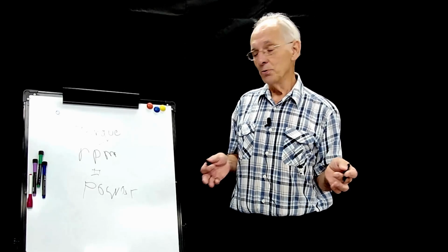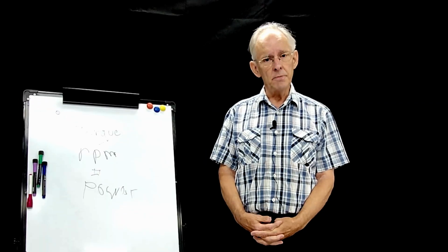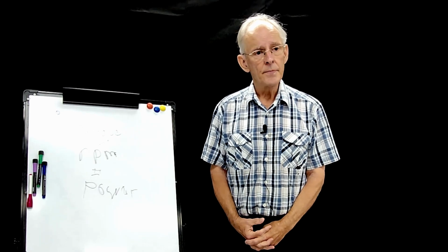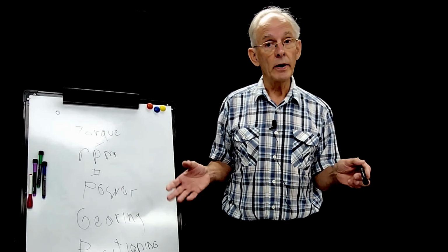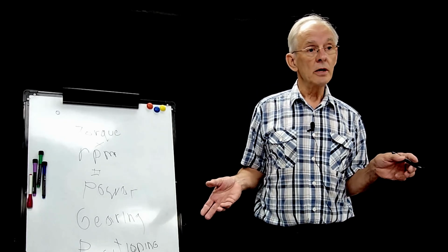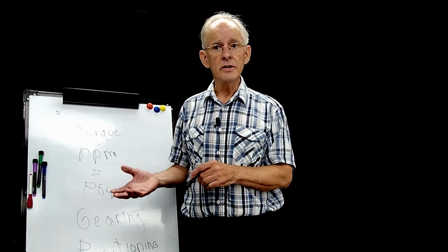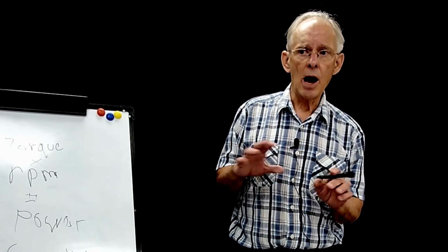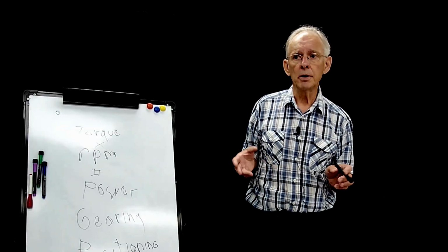Selecting a motor, you really want to know the torque and the RPMs. Decrease the speed by a ratio of 10 to 1, the torque also goes up by 10 to 1. Open loop is where there is no encoder feeding back to your controller the position. If you're going to run this thing 24/7 and you want to run it at some optimal speed, then a VFD on the AC motor is a much better choice.